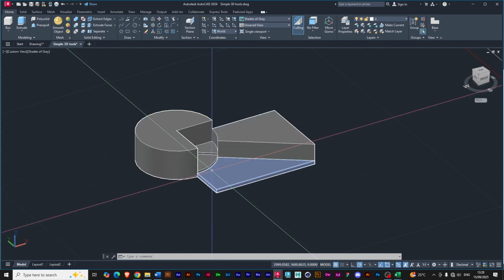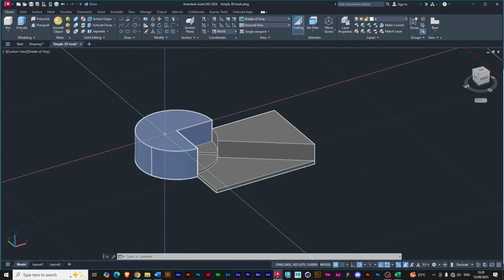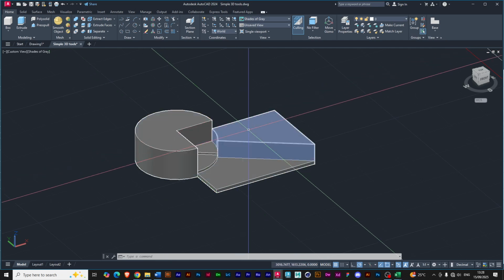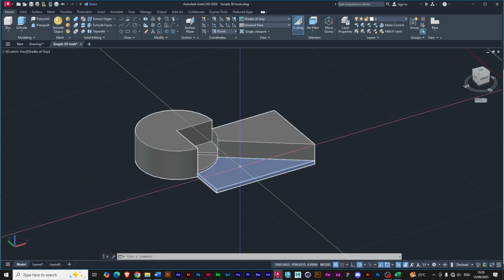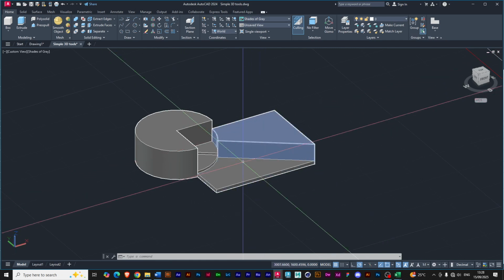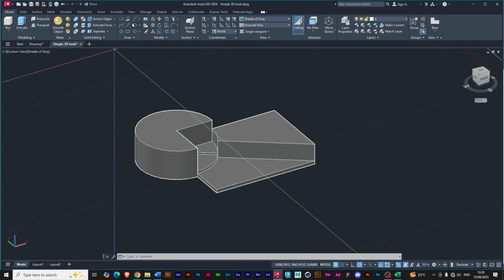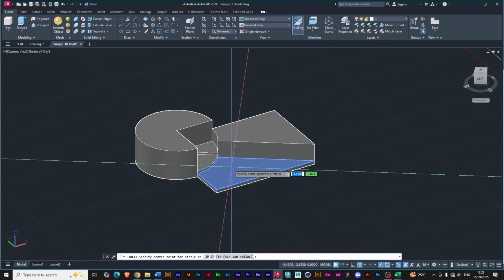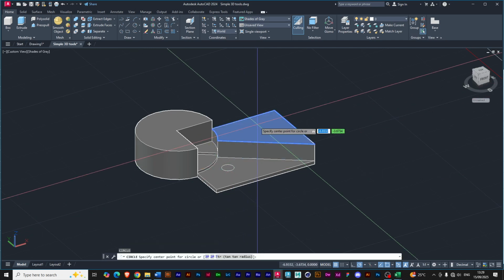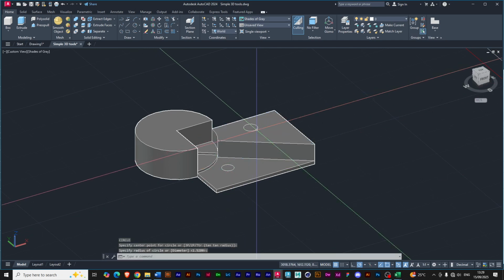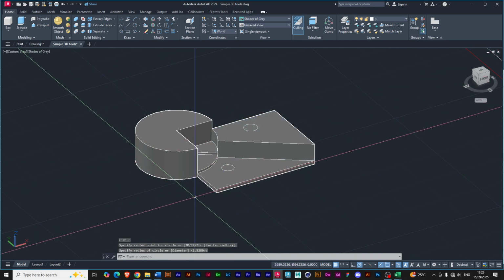Another benefit the press pull has over the extrude is the press pull can also be used to create an intrusion, like a hole, a cutout from the object. So for instance, if I wanted to make a hole on any of these surfaces here, maybe I take my circle here and click to drag that point, click to drag here. And I want to make two holes here with my press pull.